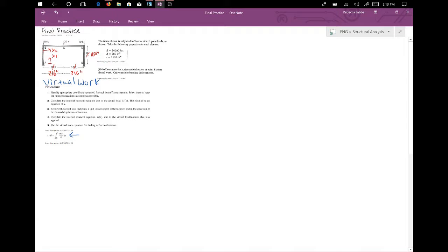And we could add x3 to start at the same place as x2 and extend past the 20 kips. That would definitely work. I think for symmetry though, it just makes sense to have it right here. And we can probably see that once we develop those moment equations for x2 and x3 that they will be the same because of symmetry. So that's just kind of, again, making our job quicker. And then x4 will just be from here. I would like to note it is not necessary, but because of the way that we have done our coordinate system, let's just add in the support reactions.